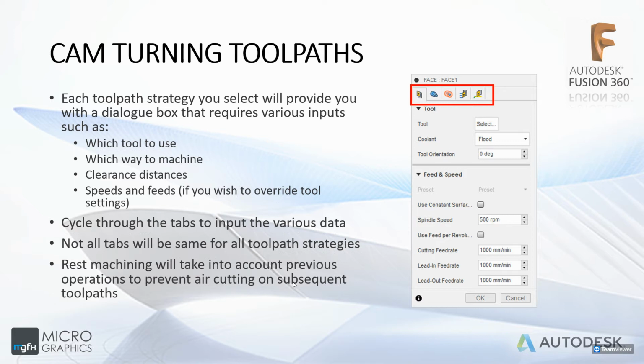Generally, the manufacturer of that tool would give you a rough idea of how capable it is and what are safe operating speeds. However, you can override these settings per operation. If you're doing a facing operation and you know this tool can handle a much higher speed to face off really quickly, you can override it in this toolpath generation menu.